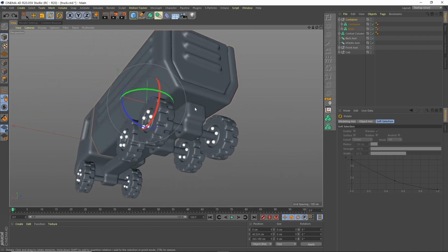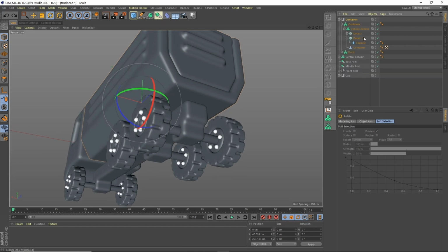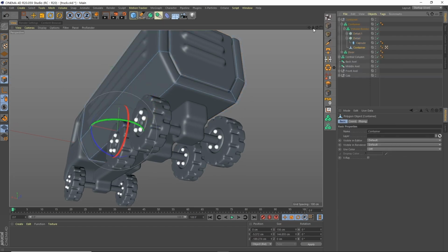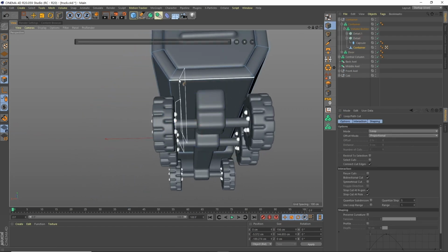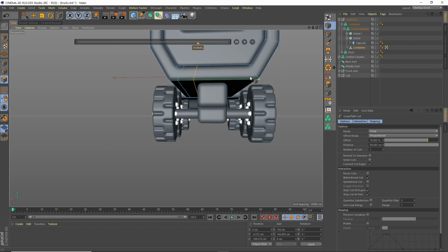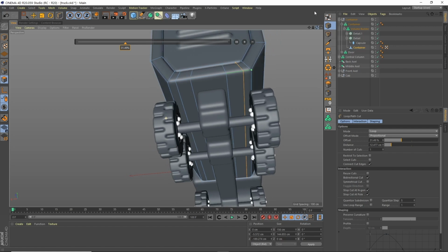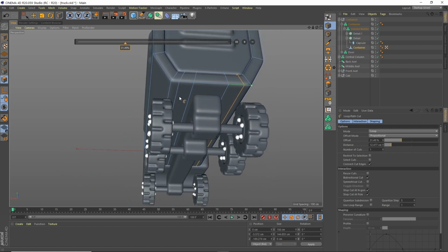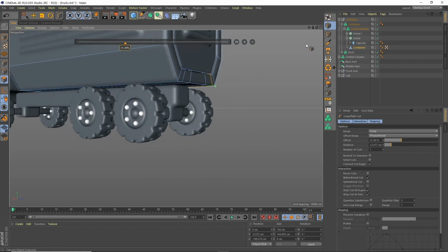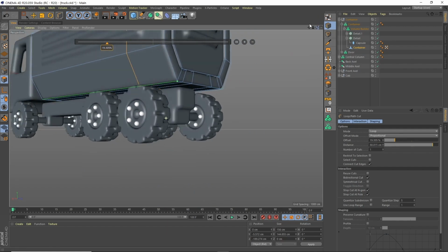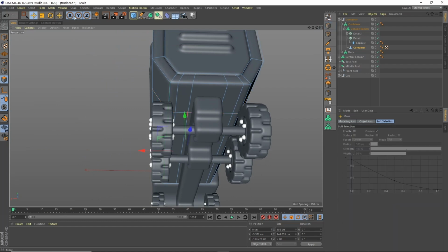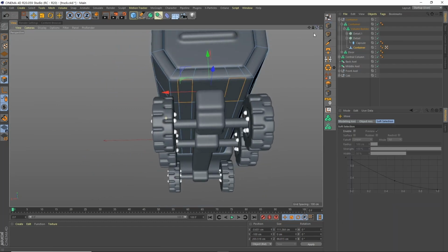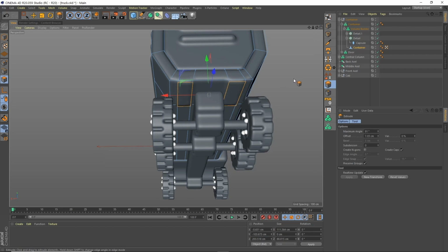So the first thing we're going to do is need to have a point in which it rotates. So let's select the container. And I'm going to need to put some cuts in here. I want it to be in between the wheel and this central column. I'm just going to eyeball it. You could do actual percentages. I'm going to be like here. And then I'm going to select these two, extrude them out.